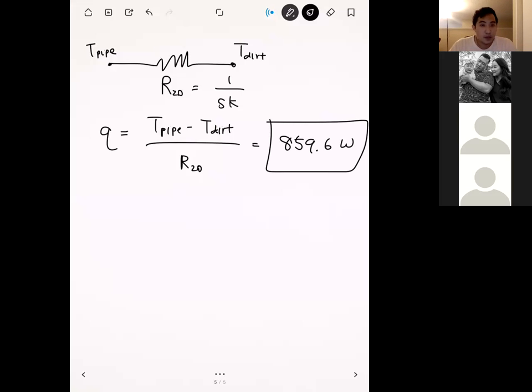Right. And so these 2D problems, as long as we're limited to the geometries that are in table 4.1, are pretty straightforward. It's basically just find the formula for the shape factor, plug in for it, and then use it in this expression here. Okay. All right. Any questions on this example?